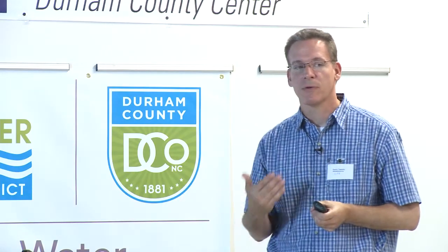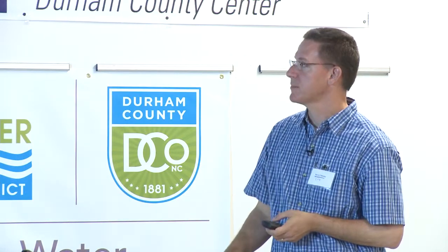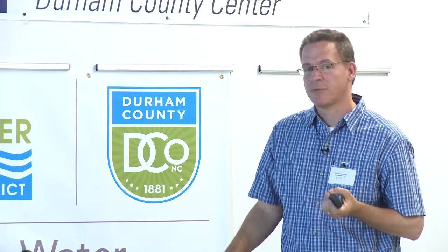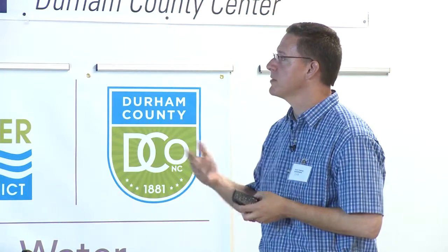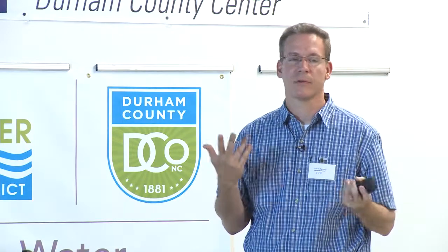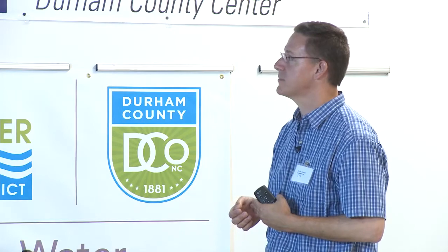I think you have to make sure your goals are attainable and practical within the constraints of your project. Let me give you an example here I think illustrates that. So let's say nitrogen reduction was one of your goals for your project. I've listed two examples here. One would be to reduce total nitrogen load to downstream waters by 10, 20%, whatever your number is. That's a very quantitative goal, and that will require a regimented monitoring program. Whenever you talk about reducing loads by a certain amount, that means you're going to have to take samples for concentrations. You're also going to have some methodology of calculating the flows in and the flows out to get to the total load. So very intensive monitoring would be required to determine if you've met that goal.